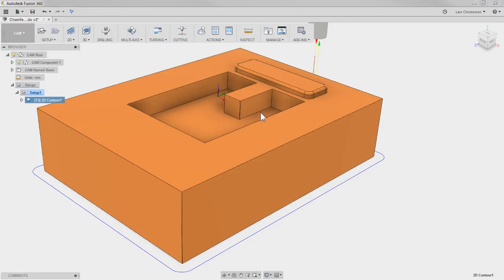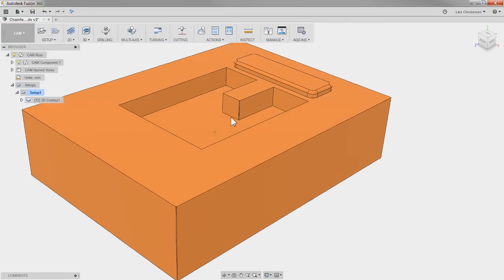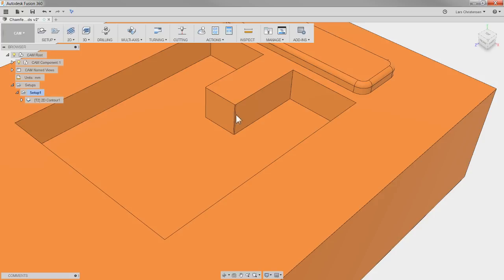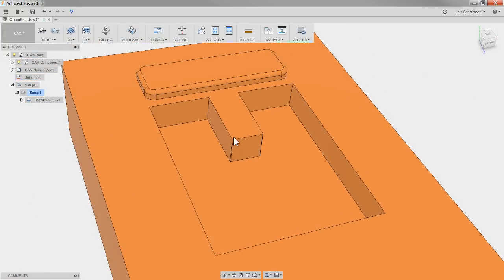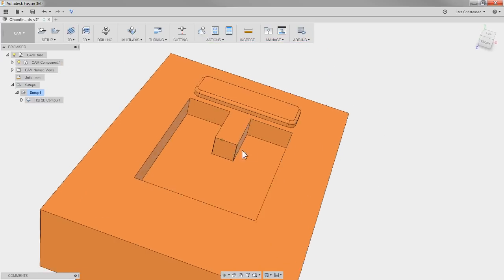I was thinking about time equals money, right? I was all about cycle time. I was all about, I'm not going to deburr my parts in the machines because I need cycle time. I need to go as fast as possible. But what I ended up realizing was that, if you have to go in and deburr, an operator has to go into the burr, that little edge in there, I mean, that's a pain in the neck right there to go in with a little needle file.